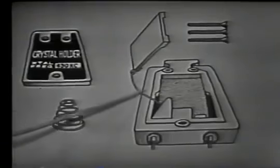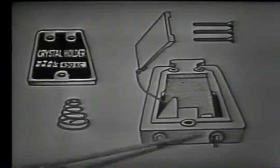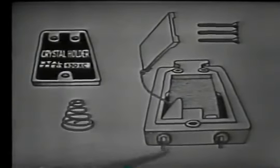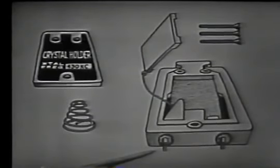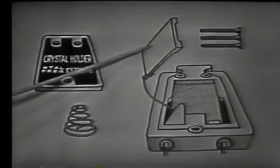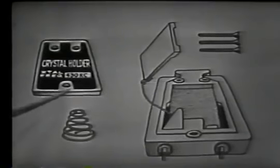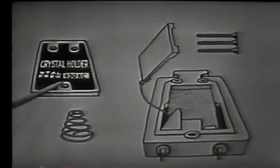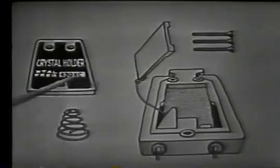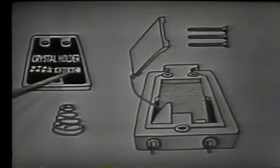The two plates then are connected to the pins. Now, these are the pins that will allow the voltage to be applied to the plate. And also, the pins will allow the crystal to be connected into a circuit in much the same manner as a vacuum tube. The spring will keep a constant pressure on the plates and hold them firmly in place. The crystal holder cover usually indicates the fundamental frequency for which this particular crystal was cut. In this case, the crystal was cut to oscillate at a fundamental frequency of 430 kilocycles.